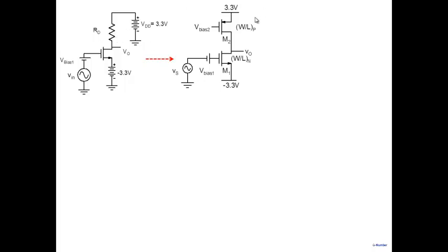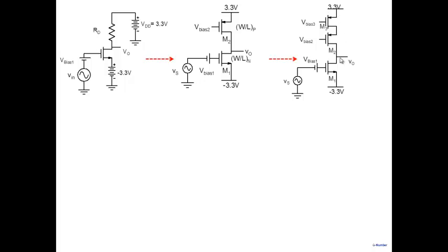All right. Now this one has a problem. If you want to build further gain, you could do this one. As I said, instead of one single PMOS, you could add 2 PMOSs here, and therefore you can build even larger gain here. Because the gain depends on the net resistance at this particular node here. And resistance looking down is R01, resistance looking up becomes very large here. And so this stage can potentially offer you twice the gain as this particular stage. All right. So you could go from here to a common source with an active stage. You could stack 2 of them to get even higher gain here.